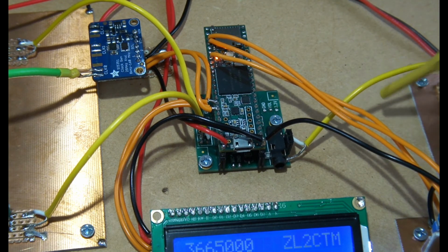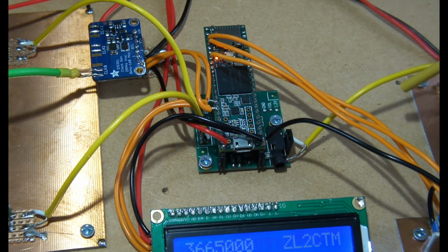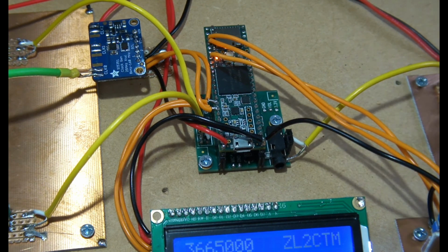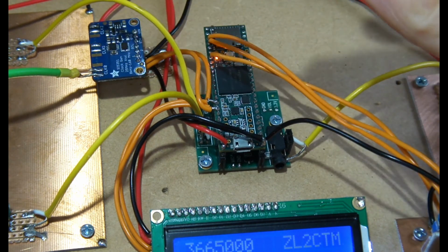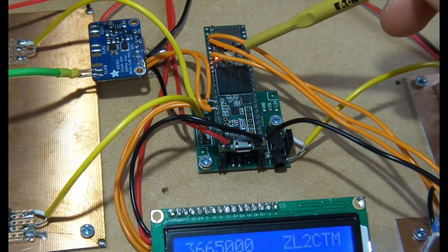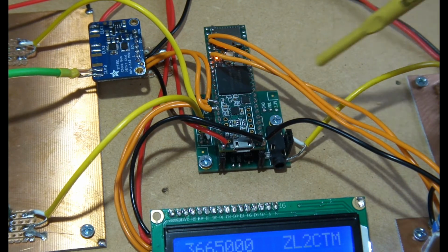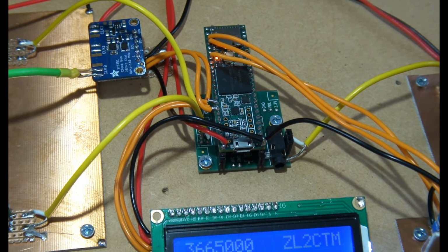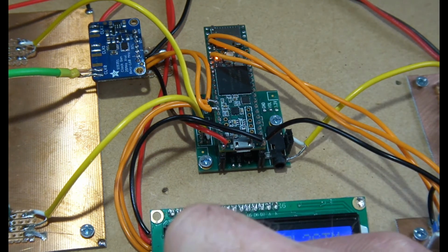Just tapped into, I think it's left, because the output of this is not going to be binaural, it's a mono output. So we've got stereo going in, which is our I and our Q. We'll do the DSP, we'll eliminate that unwanted sideband, and then we'll just output one channel of audio, which has now been fed through into that simple little audio amplifier that we were using before, that was sitting over here.